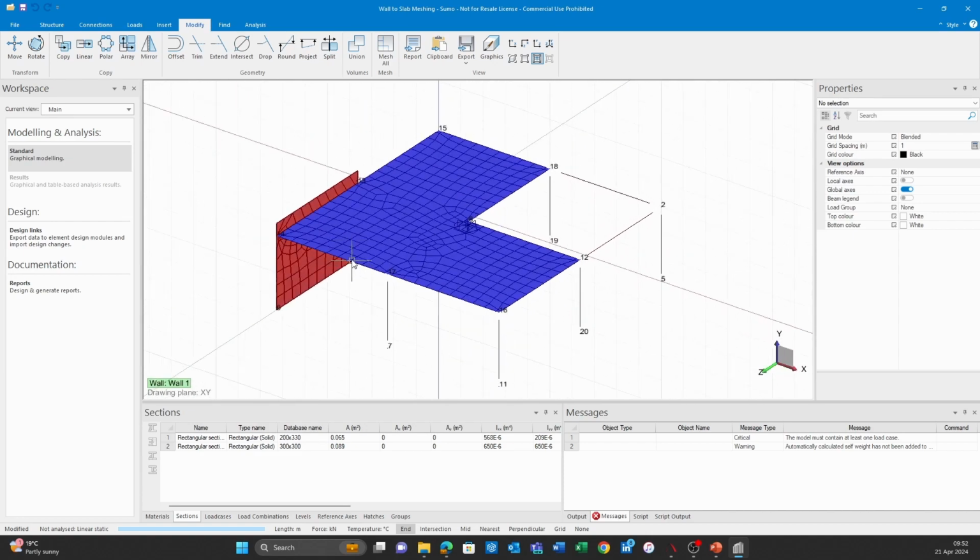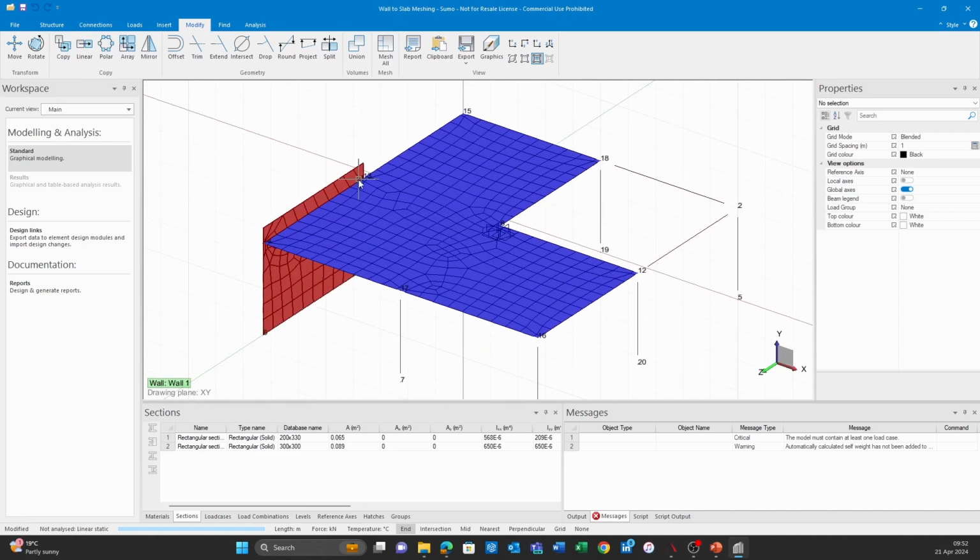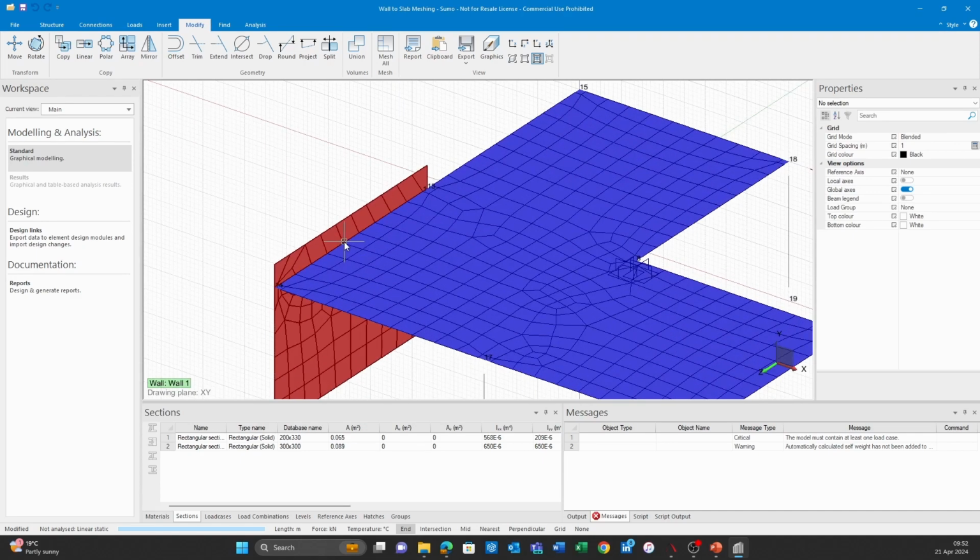In general, I know that we don't want to have less material represented in our model because we're concerned about the self-weight component. With that, you can maybe even create an area load that compensates for that, or just assign an additional live load there for whatever you've removed. So you know that you're removing 0.3 meters of that wall, you know the thickness, you know the density, and then you can assign a line load on that edge.